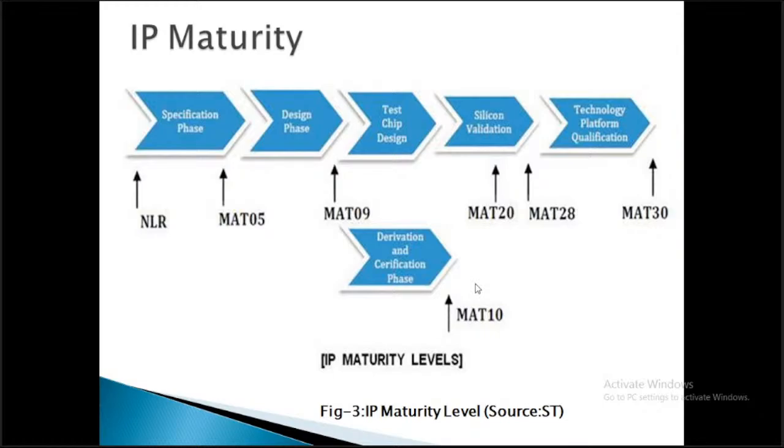After designing the layout, we go for the electrical characterization of those circuits, and we also have to define the different kinds of views which we use during the complete flow, like Verilog, or we can say LEF, DEF. Those data we need in different tools for different methodologies. Then after the final GDS, we go for silicon validation as well.